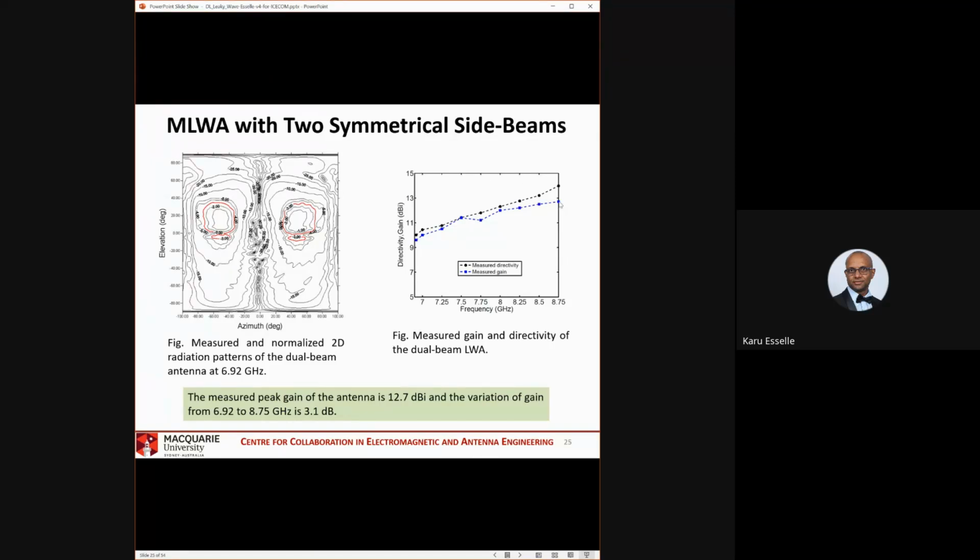That is the S21. That is the loss going to the match load. So at higher frequencies, we have some power terminated, going to the match termination, and as a result, radiation efficiency decreases. So a gap emerges between directivity and gain.